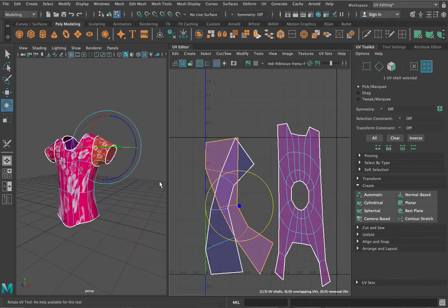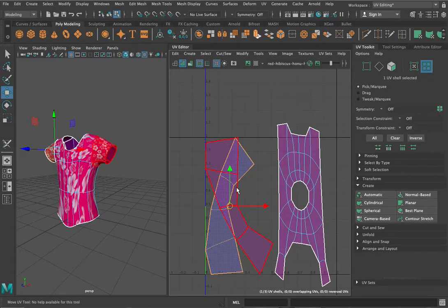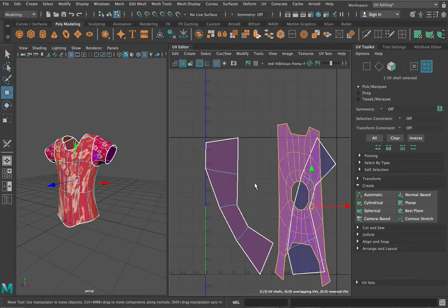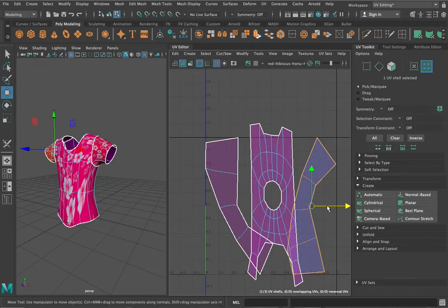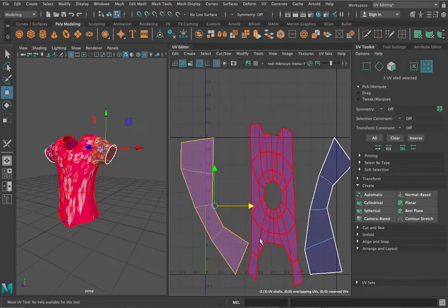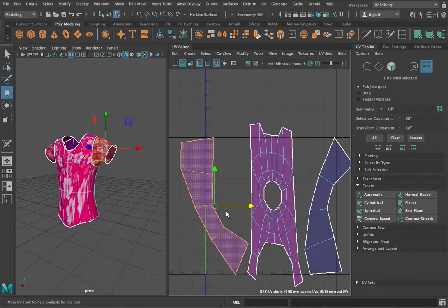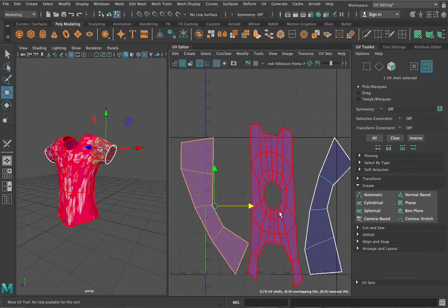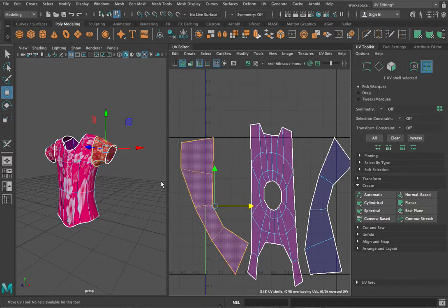So this wasn't a good way to cut it, but the main point about showing you this is that it gives me an opportunity to, because I've got complete cuts around the arms, bits have come off separately. So I can actually texture these separately. Now this is really useful, doing things like this, breaking a single mesh up into smaller parts, can be really useful when you're texturing something like a car, because you'll want the tires and the different parts, like the doors, for example, as different mesh objects as far as the UV mapping is concerned, and this is a good way to do it.